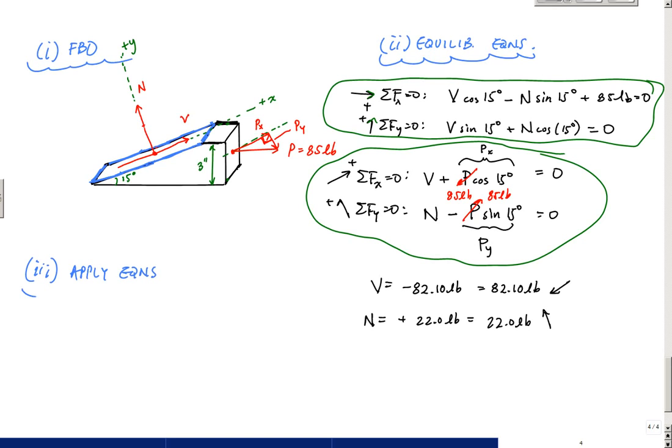We need some geometric properties, in particular this blue zone, which I'm going to call A star. If you remember, this width right here is 1 inch, and the original cross-sectional area is length times width, which is 3 inches times 1 inch, which is 3 inches squared.